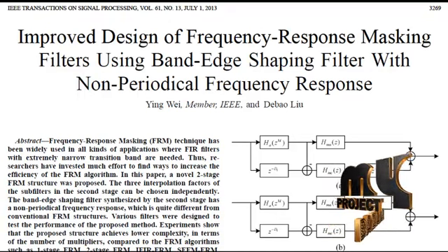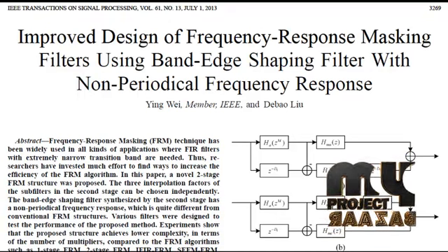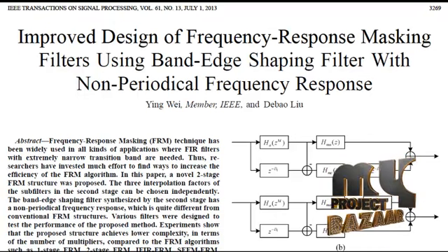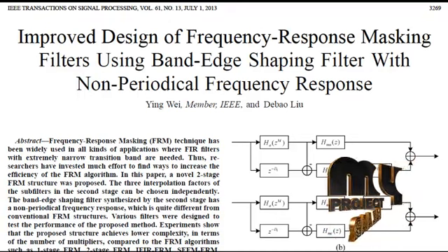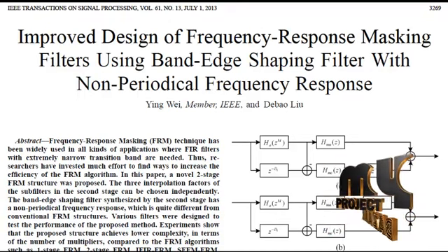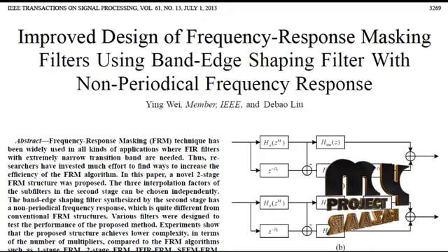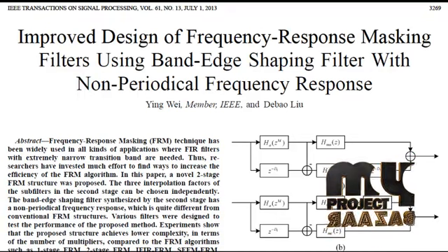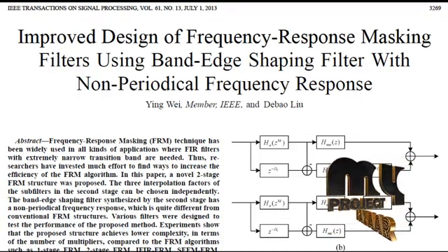The main aim of designing these filters is to reduce the complexity. So, the drawback of FIR filter is overcome by frequency response masking technique. In this technique, first of all, the filter is interpolated to get the transition band. Then, the interpolated filter and the complement are masked. Finally, the result is obtained by combining all these together. This leads to low arithmetic complexity.